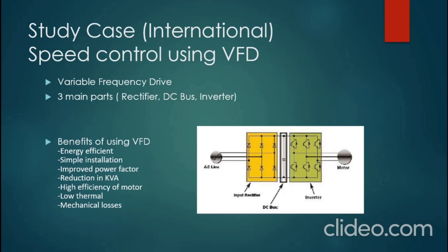By doing this, the output voltage frequency will be doubled, but the sine waves are still in the ripple state, which needs to be flattened out. This is where the DC bus plays its part. The ripple wave from the rectifier then passes through the filter, which is a capacitor, which then smoothens out the wave into DC output. The inverter converts the wave back from DC to AC, but not before the sine wave goes through PWM, which is pulse width modulation.